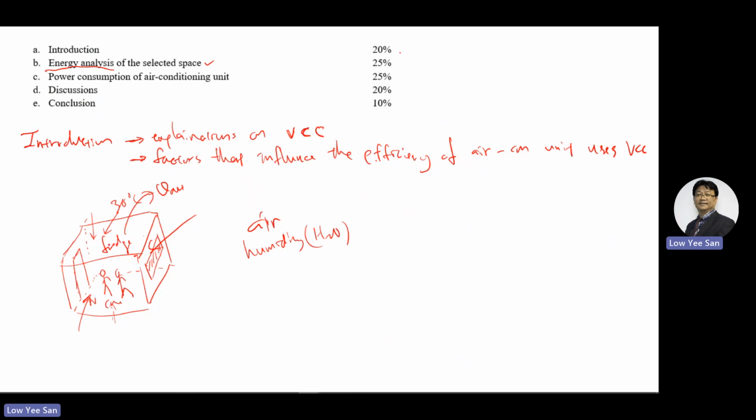That's why an aircon room is a bit dry, as people know. The humidity tends to become lower after air conditioning because the water vapor is being removed. So literally, you are cooling down the air and also the water vapor. If it reaches the dew point, the water gets removed from the room.